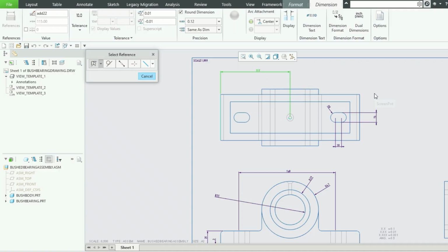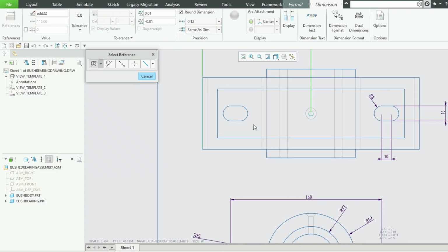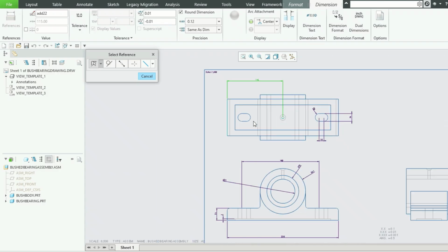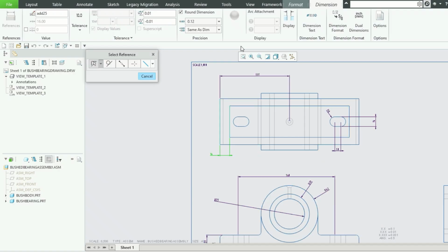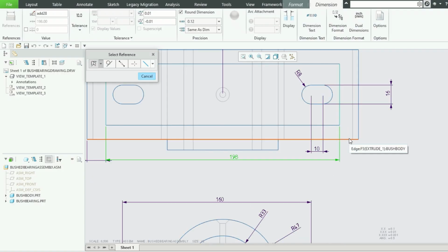What else? We want the center to center distance. We can give 160 mm, 60 mm. From where it starts, this edge to this edge, it should be 60 mm, right? And this overall cutout dimension is 158. And this to this is 12 mm.